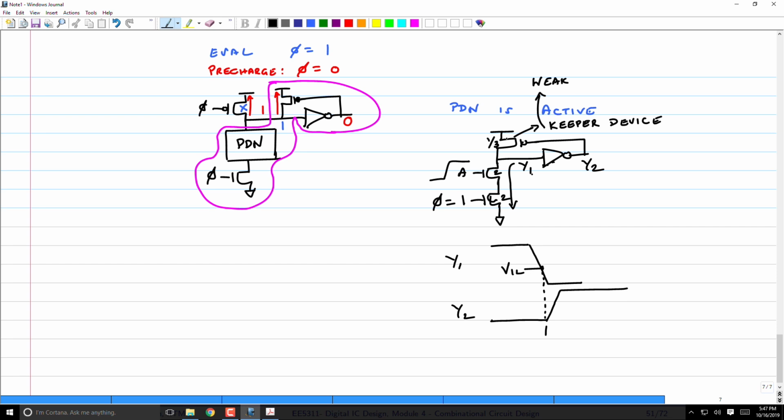Question is, can I make a transistor with size 1/3? For the logical effort discussion, it was okay because whether it's 1/3 or 1, it doesn't matter as long as the relative sizes are okay. But in reality, if I want a transistor with 1/3 and that's not possible, then what do I do?